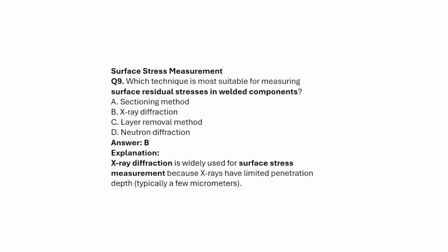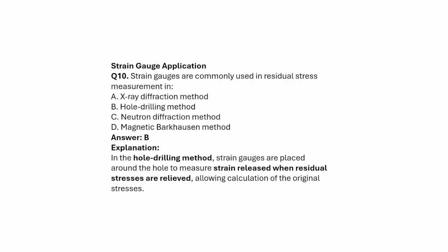Neutron diffraction is not destructive, but it is a much more expensive process. So X-ray diffraction is widely used for surface stress measurement because X-rays have a limited penetration depth, typically a few micrometers.